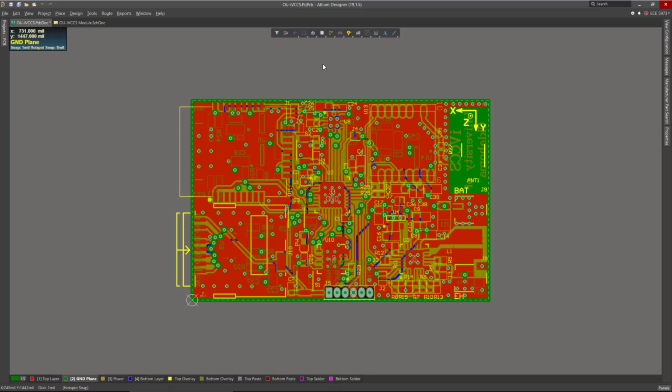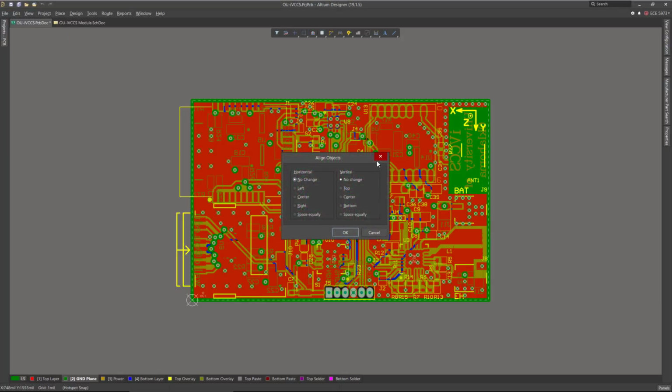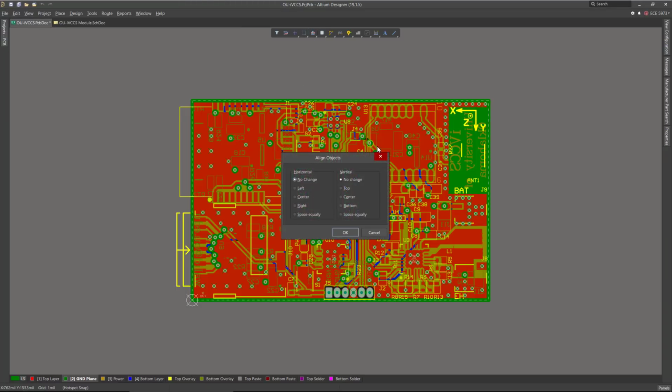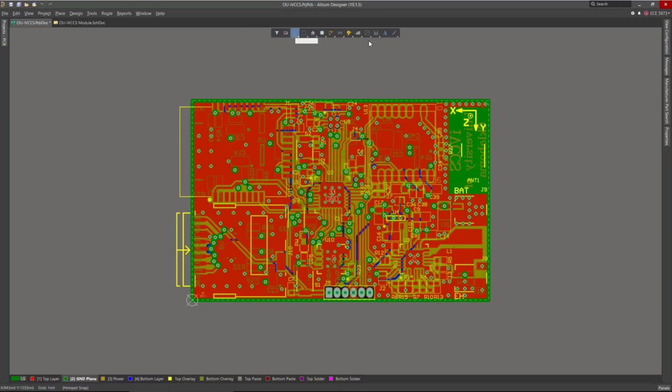Now you can select a command from the active bar by left click on the mouse. So move, just left click. To release the command, just right click on the mouse, it will release it. So left click to select, for instance, move, right click on the mouse to release it. And if you hover the mouse over these commands on the active bar, you will see a tooltip describing the associated command or the process you are hovering over.